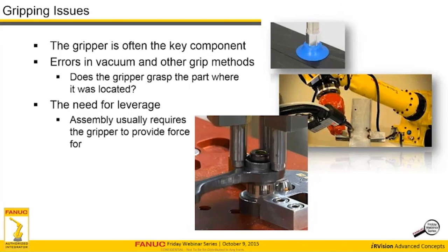In this case, the design of that tooling has been correctly put together such that the tooling not only grips the part, but grips it in a way that provides a positive force without changing the position of the part as it goes onto the bearing. This happens more often than you might think in an assembly application, and is, again, the source of some potential error as you design for your best precision in assembly.